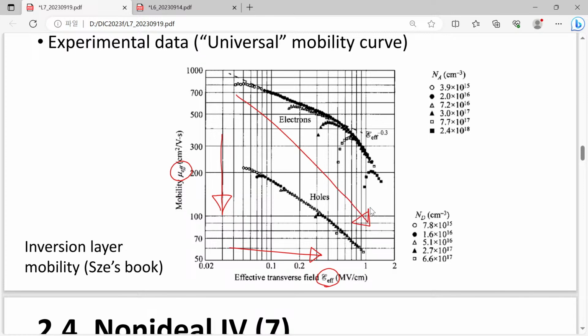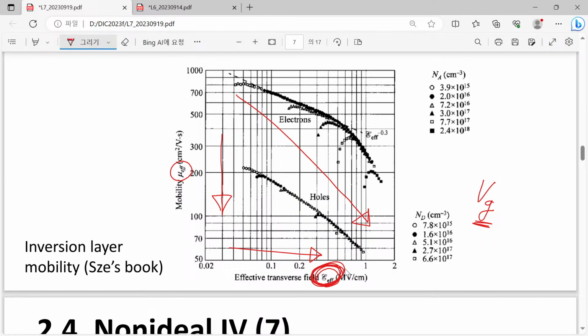Then please try to consider what is the direction of your gate voltage. Up to now we have thought about electric field, but how about gate voltage? In the case of your N MOSFET, the direction of increasing electric field exactly matches the direction of increasing gate voltage. So when you give the transistor higher and higher gate bias, you collect more and more electrons.